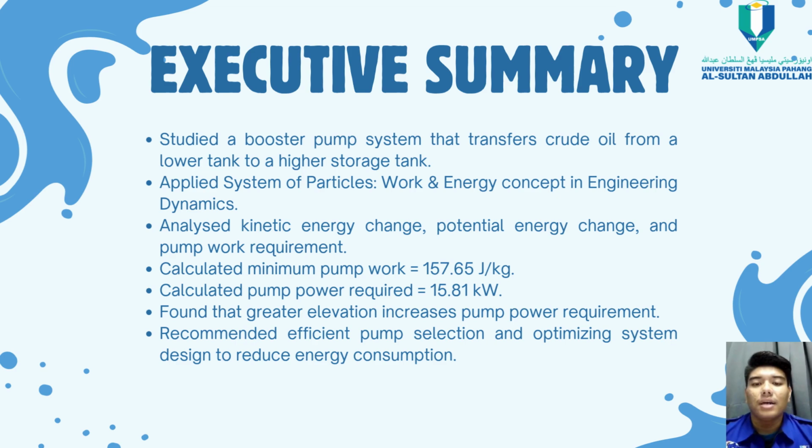From our analysis, we calculated the minimum pump work required as 157.65 joule per kilogram and the pump power required as 15.81 kilowatt. The results show that as the elevation difference increases, more pump power is needed. Therefore, proper pump selection and efficient system design are important to reduce energy consumption and improve petroleum transportation efficiency.